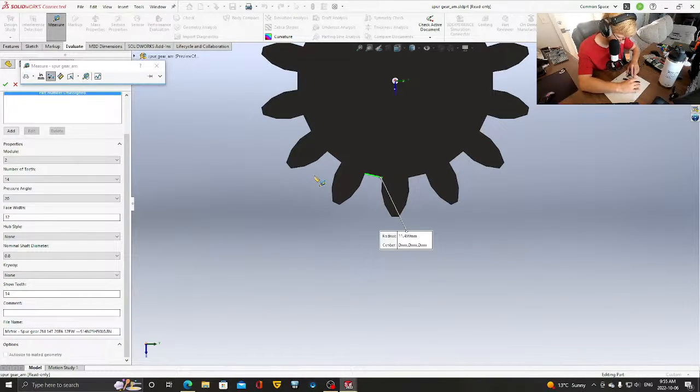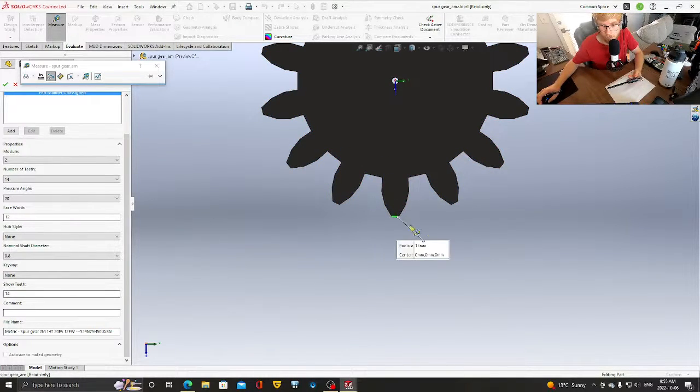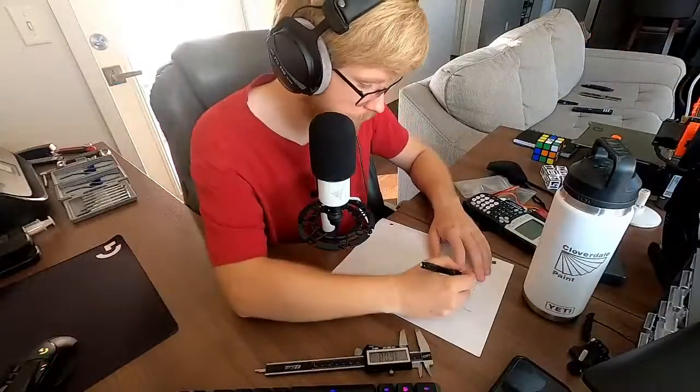Let's get a couple other marks just to get an idea for the circle better. Circle goes to there, except that's not the final teeth destination. We will need 16 wide, was it? 16, yep. 16 mil wide. So that is as close as we will want to get. So make that the center of our circle.